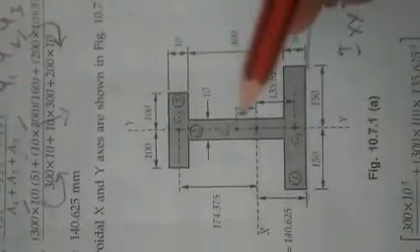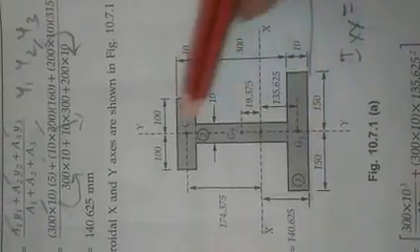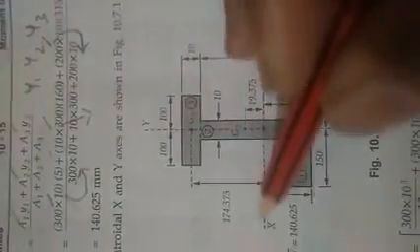So what is this y1, y2, y3? This is very important and a little bit complicated. Be very clear and crystal clear in finding y1, y2 and y3. I will teach you how to find this y1, y2, y3. See here, whatever the given section is, I divided the section like this. 300 is the length, 150 here, 150 here, and 100 here, 100 here. Exactly I cut at the center. So you have to find out this centroid.